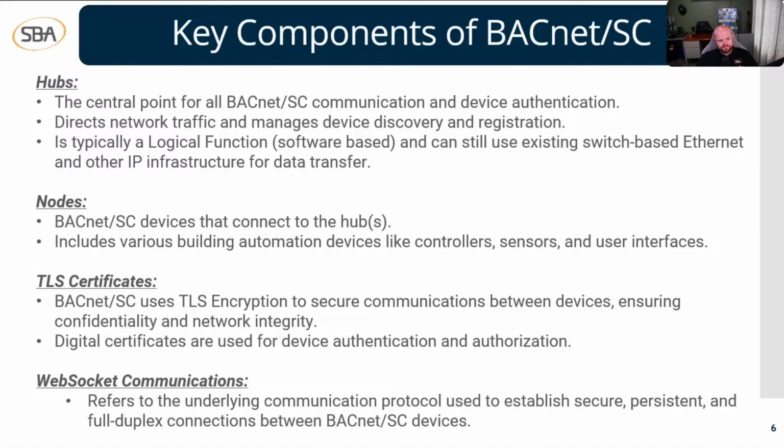So that's nodes. Next thing is the TLS certificates. And again, this is the big idea with BACnet Secure Connect, being able to encrypt these data packets. So with TLS certificates, BACnet Secure Connect uses TLS encryption to secure communications between devices, ensuring confidentiality and network integrity.